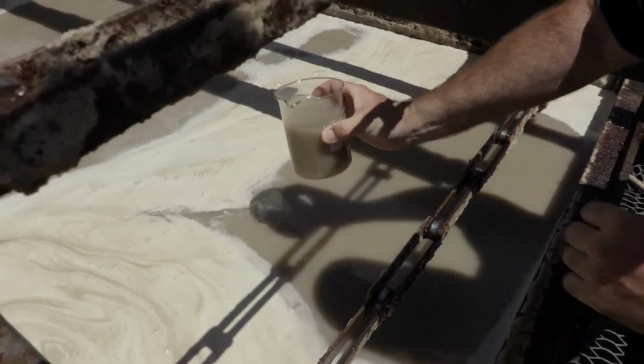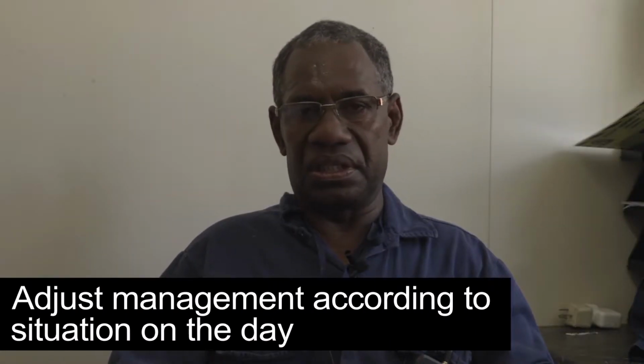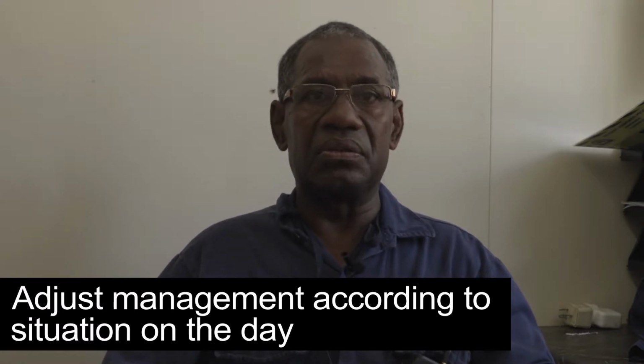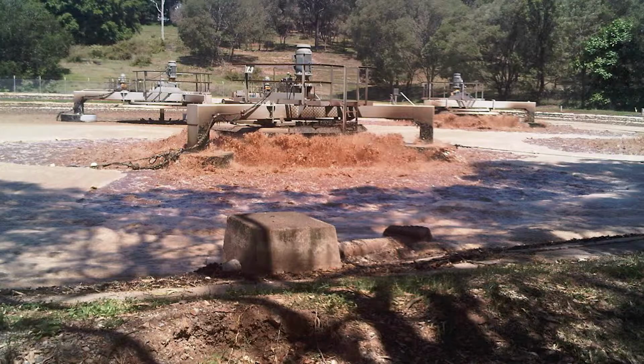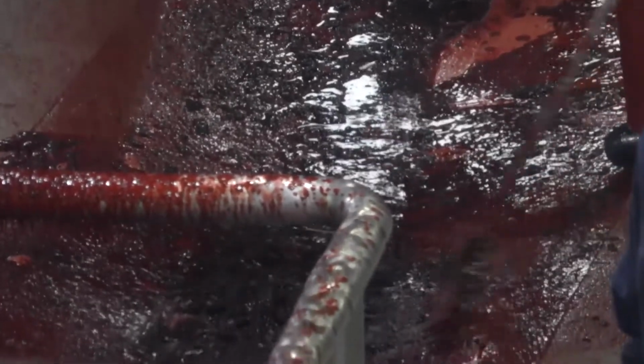Operators of upstream wastewater treatment plants also need to continuously monitor for changes in the wastewater stream. The operation is not the standard that you set once in the morning and it will work all through the day. During the day, you can't change how you operate the wastewater, because you never know what waste is coming through the production, so you just have to monitor. In the event of blood coming through or tallow coming through, you immediately inform the supervisor or the production manager. Tallow and blood are easy to identify because they change the color of the water. The sticky water is very hard to see. The next morning you'll pick it up on the data readings and then inform the production manager straight away.